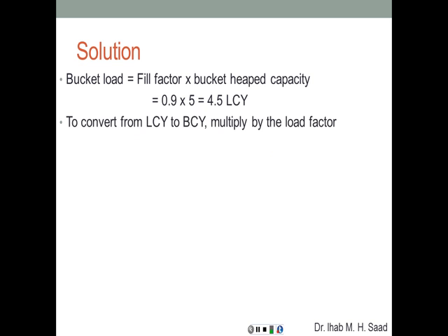Then we need to convert these loose cubic yards into bank cubic yards. So we're going to multiply by the load factor. So that's going to reduce the volume. Therefore, each bucket is going to carry 3.6 bank cubic yards for each cycle.